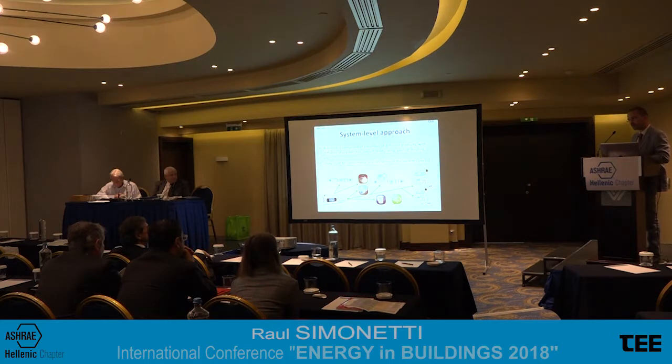Number four can be the minimization of the water used, in case you have humidification and evaporative cooling systems. With those you can do cooling in order to reduce the energy used by chillers for doing cooling. And a fifth one can be the maximization of the outdoor air intake if you need air changes inside the conditioned environment. So systems are a bit more complicated than products because they may have different hierarchical goals, and depending on those, they have to be controlled in order to fulfill all these goals. But energy savings can be of that order of magnitude.